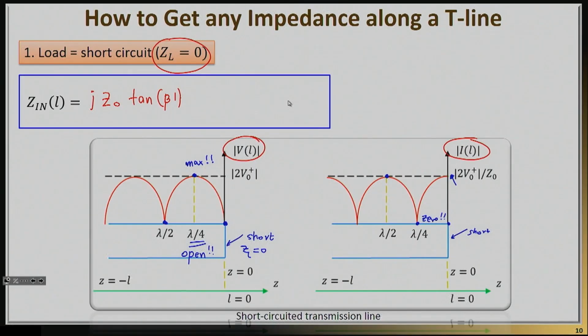So this idea of essentially changing impedances between short and open, or open to short, in a short transmission line is very, very powerful. And again, it only takes a quarter of a wavelength to make that happen. Now, of course, when you were taking undergraduate courses and designing circuits, usually those circuits were at very, very low frequencies, which meant that lambda was a very large number. If you're designing a circuit at 1 megahertz, lambda is really large compared to the physical dimension of your circuit, so you will never see that effect. But when lambda starts becoming 1 centimeter, 1 millimeter, then very quickly, unless you're very careful, you can run into trouble.